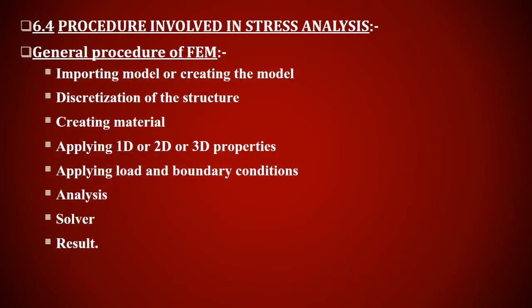The procedure involved in stress analysis is the general procedure of FEM. FEM, everyone knows, is finite element analysis, a part of structural stress analysis. First we import the model or create the model. After that, discretization of the structure, which means meshing of the structure. After importing the model from CATIA software, we mesh the material in NASTRAN PATRAN software.